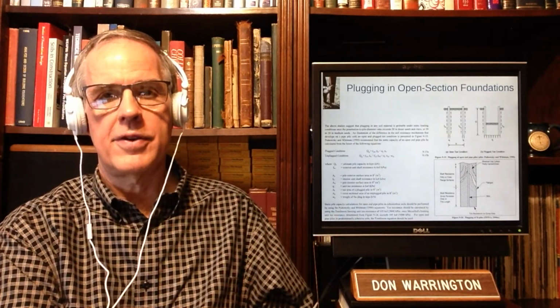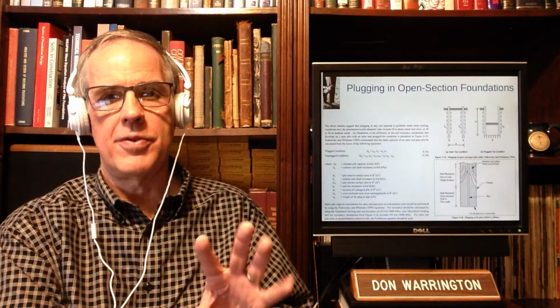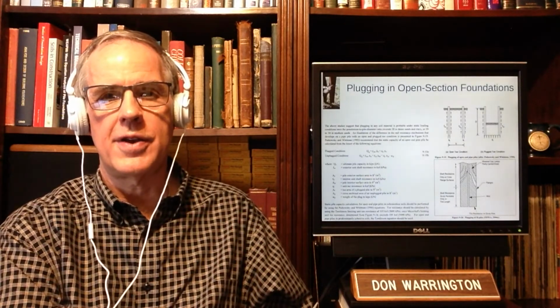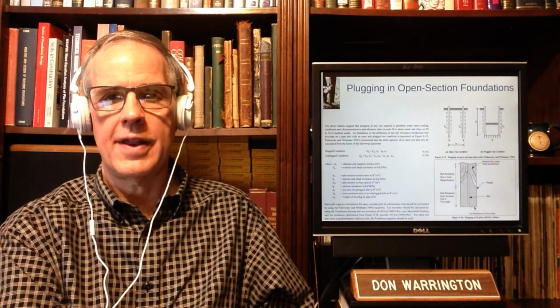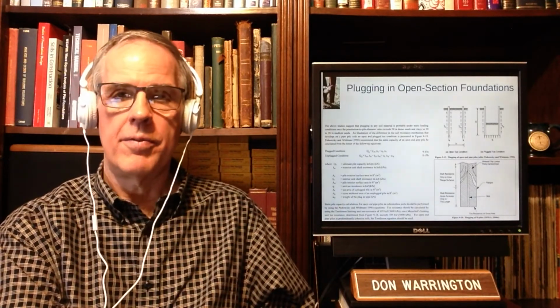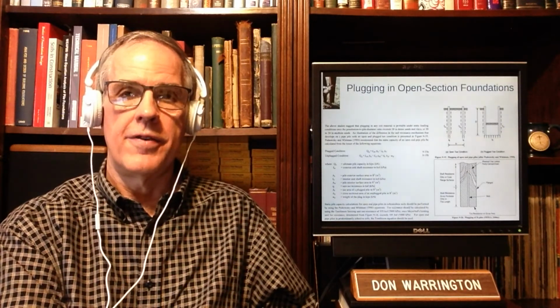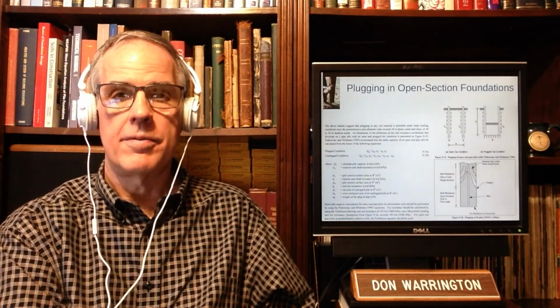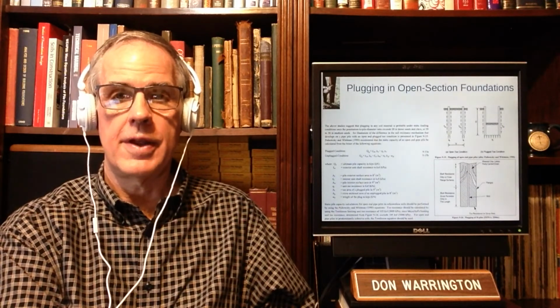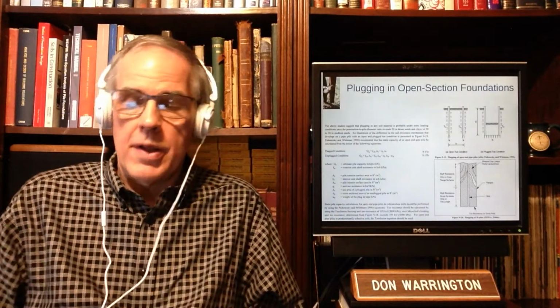Estimating it has traditionally been done using a statics method to figure out how deep the plug is. Plugging can definitely affect the drivability of a pile, and severely in many cases. So plugging is an important issue.